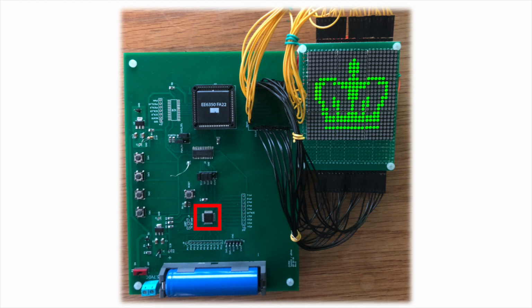The microcontroller we have used is an ARM Cortex M0 microcontroller. The microcontroller supplies 5 signals to our chip: clock, clock 2, reset, data, and data latch. These 3.3 volt signals are first converted to 2.5 volt signals by a logic shifter before driving our chip's 2.5 volt inputs.